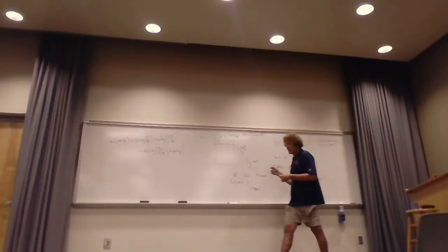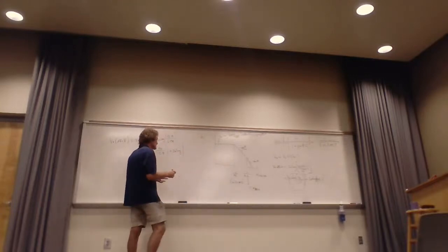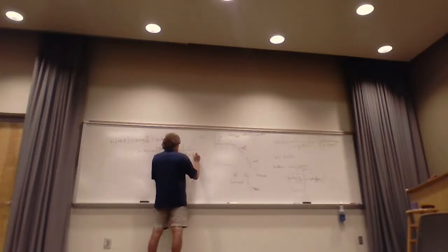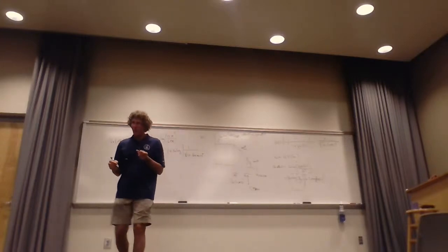Do y'all agree with that? Just so everybody knows. So this is going to be 1 over the square root of 1 plus, now omega is 2 pi f, and that's at 90 megahertz, so it's 2 pi times 90 times 10 to the 6, right? Times R times C. Was R 100?